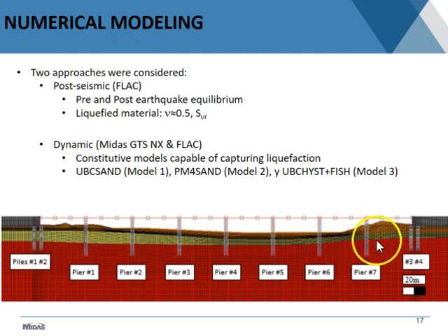Of course, you have to build this in steps. First of all, you have the natural soils, then you put the fill, and then you put the structure on top, and then only with the gravity acting, you let the model reach equilibrium. Right after you do that, and here I'm thinking a little bit about FLAC, you change the properties of the liquefiable soil and then let it go and see what type of equilibrium condition the system finds.